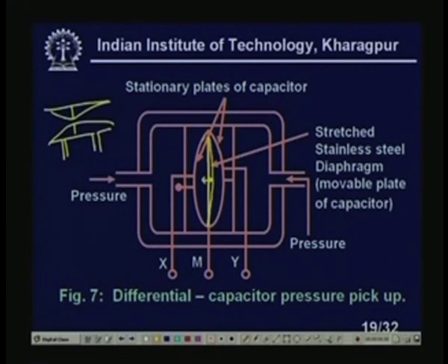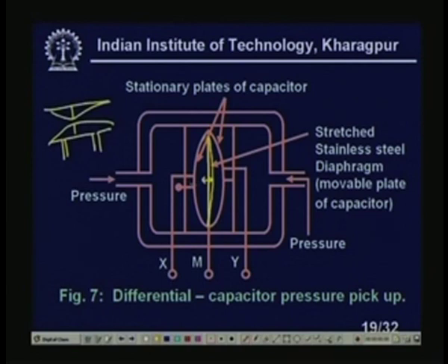Actually, in the process you will find that we are using a pressure capsule. The pressure does not necessarily come directly here, because this liquid will come down here, and in between there is another liquid, which in turn makes a pressure on this side, so that the diaphragm will be stretched like this, right.